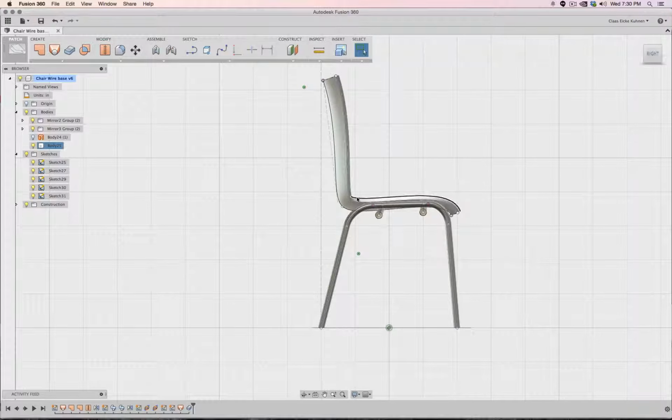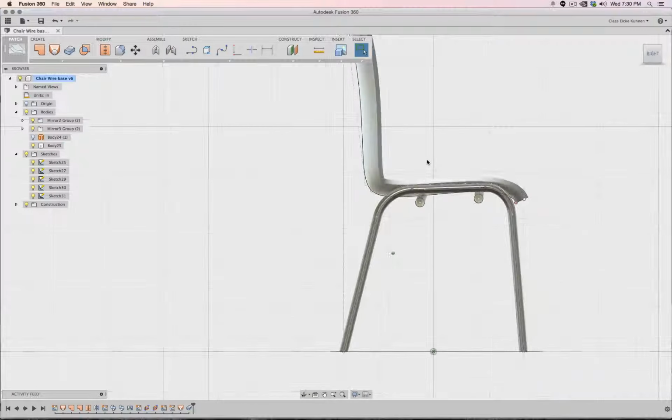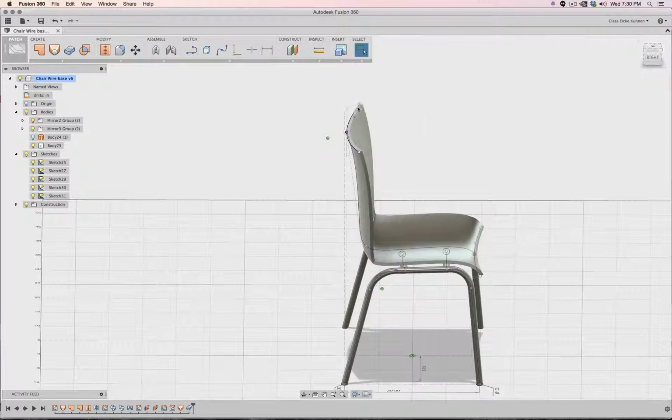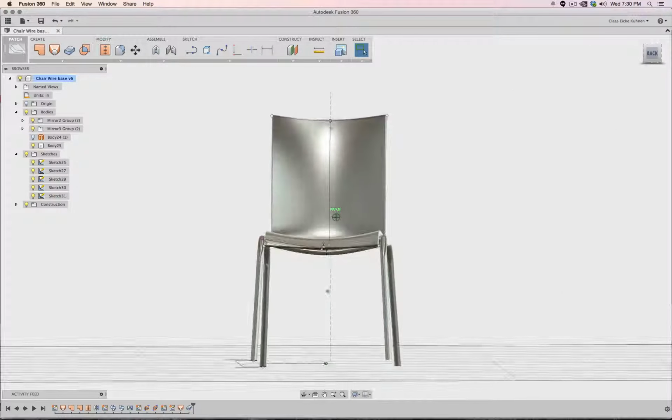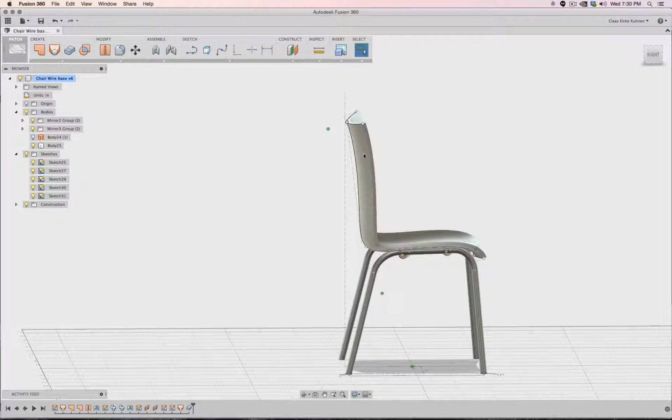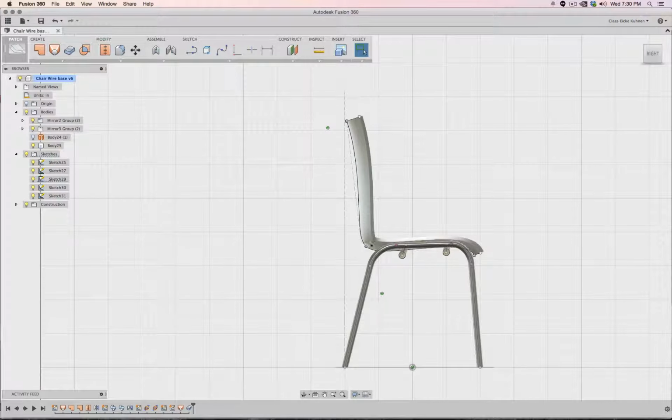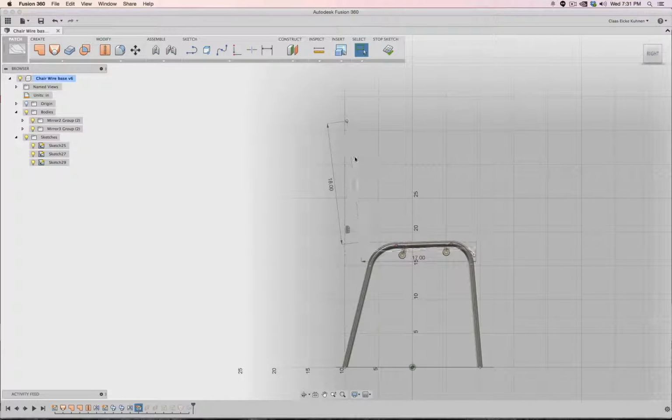You see here, this part looks a little bit pinched, and that is because this arc gets bigger. You see here, this arc is a little bit smaller, and those two C's are run along this line. So here, where this point is, that curve is a little bit too small. So to prevent this pinching here, I either have to make this upper arc flatter, which I don't really want to do. So I'm simply going to go into edit mode here, click this one.